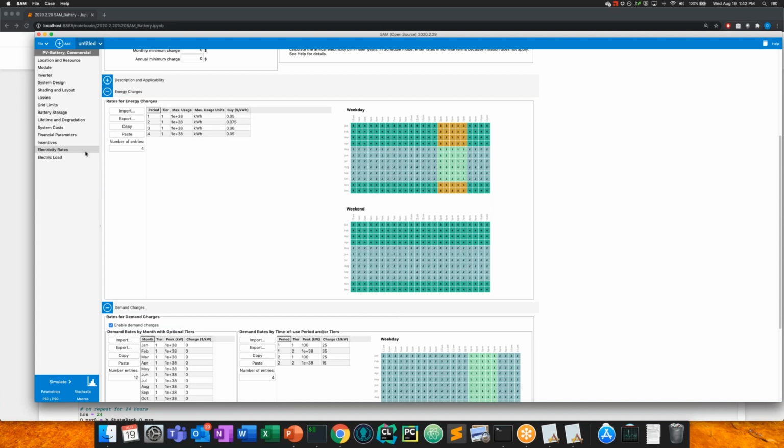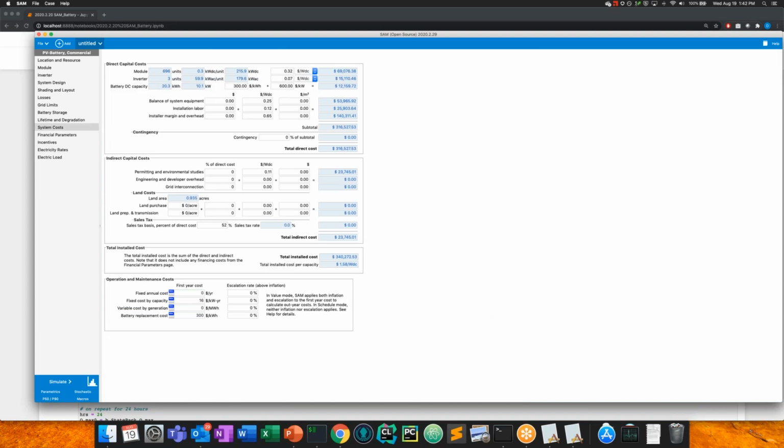So another set of inputs to the optimal sizing functionality is the costs. The battery costs are multipliers in dollars per kilowatt hour and dollars per kilowatt. And this will help REopt decide how to make the trade-off between a bigger battery and having more electric bill savings. Likewise, the battery replacement cost helps determine how much to cycle versus not to replace.